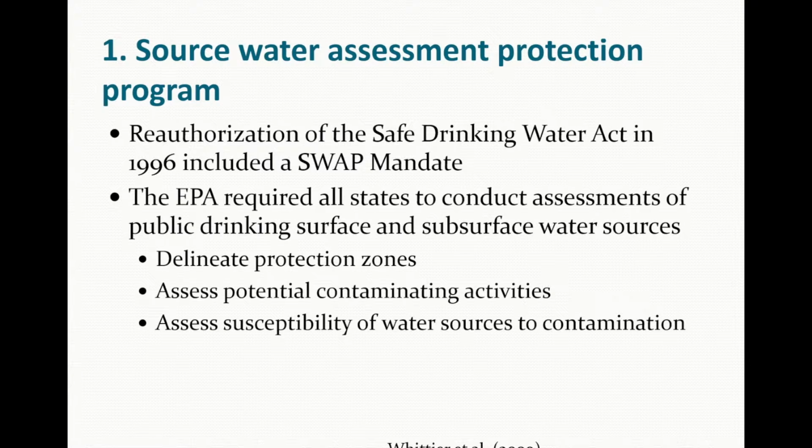And the process includes delineating the protection areas, say around the well, and assessing potential contamination activities, identifying all potential sources. Could be actual or existing sources if they have the potential to leak, such as gas stations, factories, military bases, agriculture, etc. Then estimate the risk for each source to identify the relative risk, high risk, low risk for each individual source.